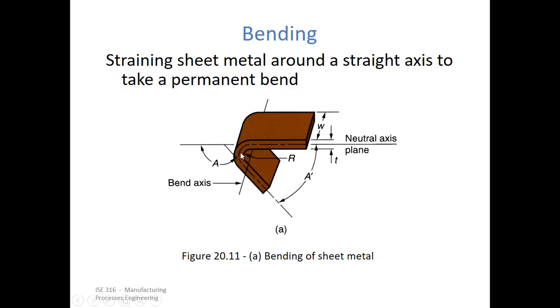right? So those cracks, if they are to be avoided, this R has to be taken into account. How much you can bend it depends on how small or how big the R is. It depends on the value of the radius of curvature. It also depends on the timing of the bend. If it is suddenly bent or you are allowing it time to deform would also matter.